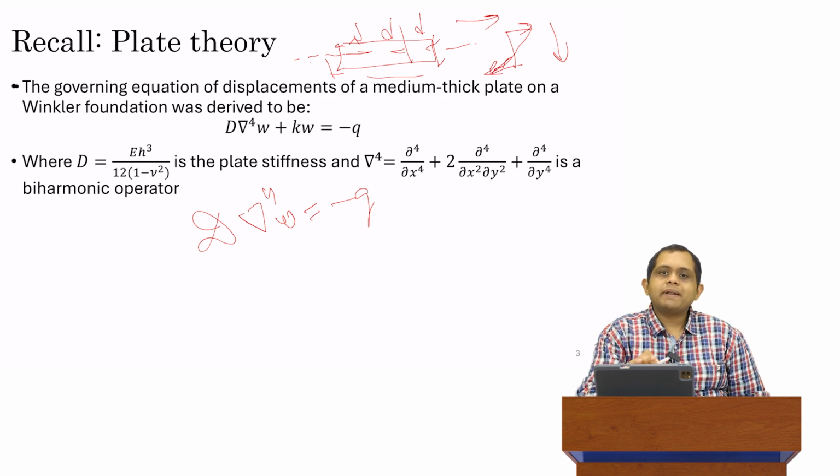And remember, we're talking about plain concrete slabs over here. These do not have any internal reinforcements. We're not talking about reinforced concrete, which is a separate theory by itself. So we have these plain slabs, and then we have a neutral plane. At the neutral plane, stress always remains zero.